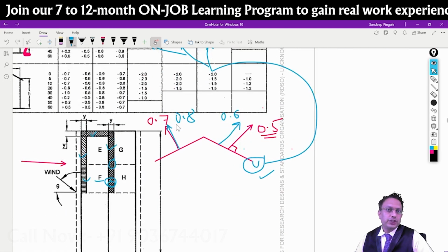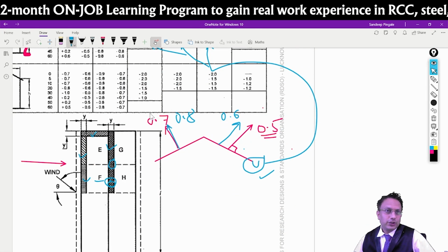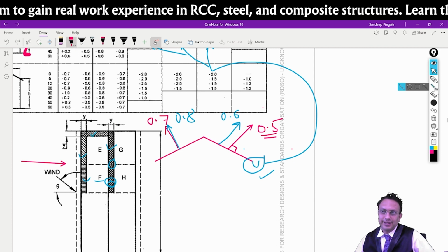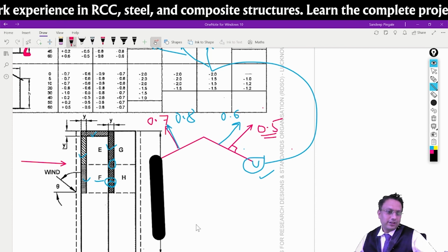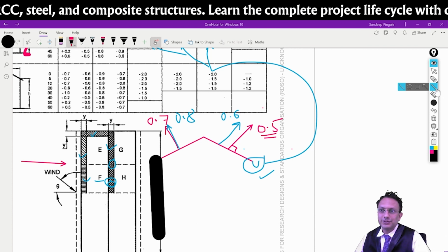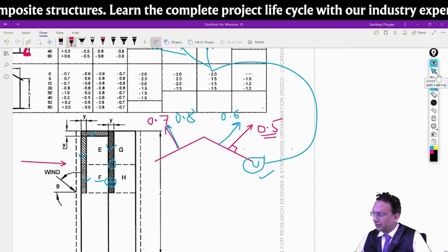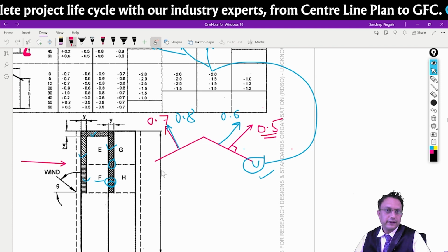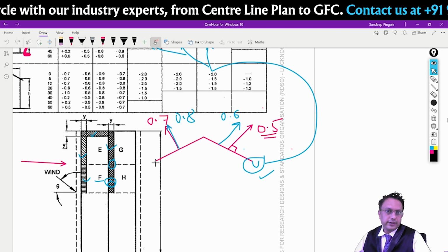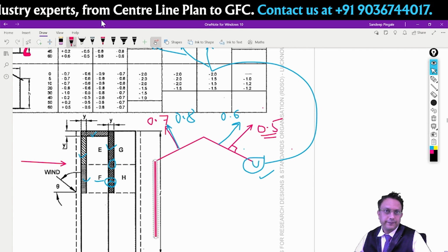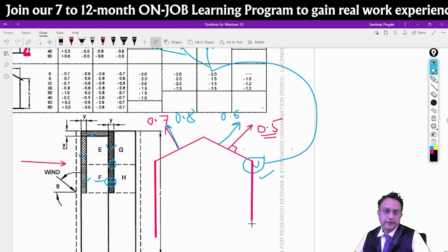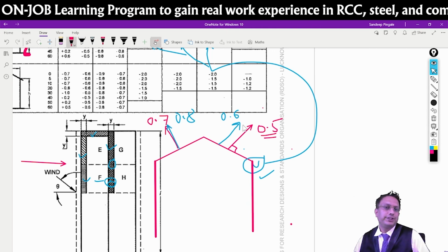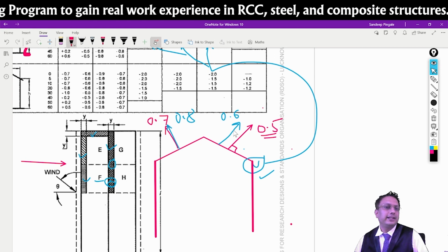Understood? Now we have seen for the pitched roof, this is the sloping roof. Now what actually will we be seeing for the building? Where is the main building? Sorry, today my digital pen is not working, unfortunately. All right. So this is the main building. So on the roof, I have identified 0.7, 0.8, 0.8, 0.6, 0.5, which is for 0 degrees and then 90 degrees.